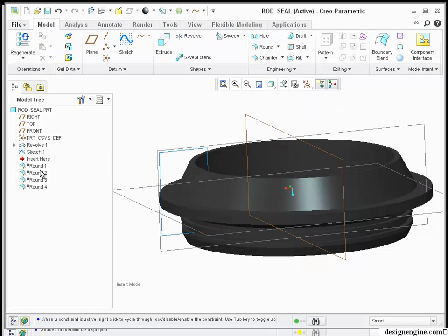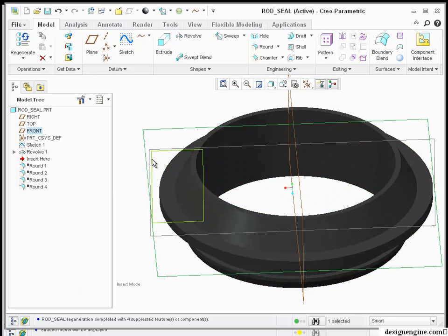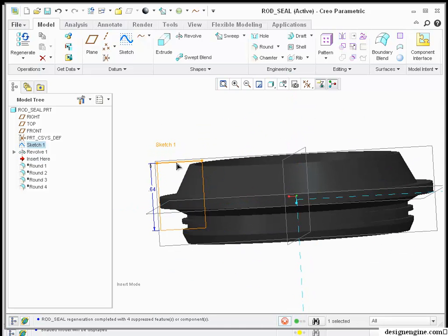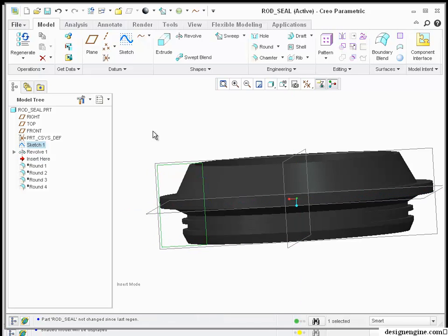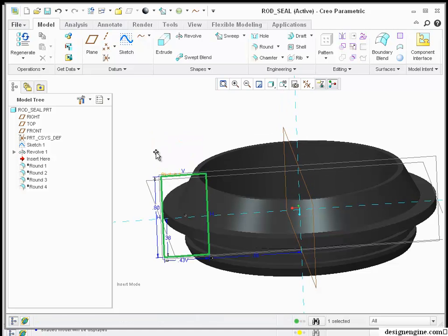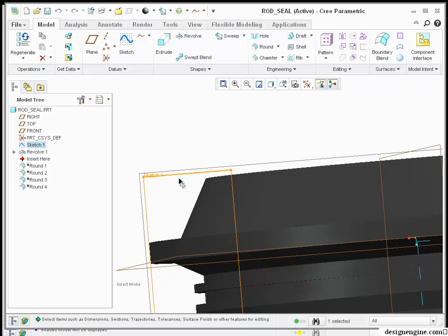I was careful not to dimension to anything, and I'm going to reorder it ahead of time. Then I'm going to take and modify that underlying curve geometry. Notice how I can do all that in real time. It's like the regeneration button's been done away with. It just automatically regenerates. I did hit Control G at the end there to get it to update, but I could have just, as I make a modification, left click up here somewhere, and it still does the regeneration for you.